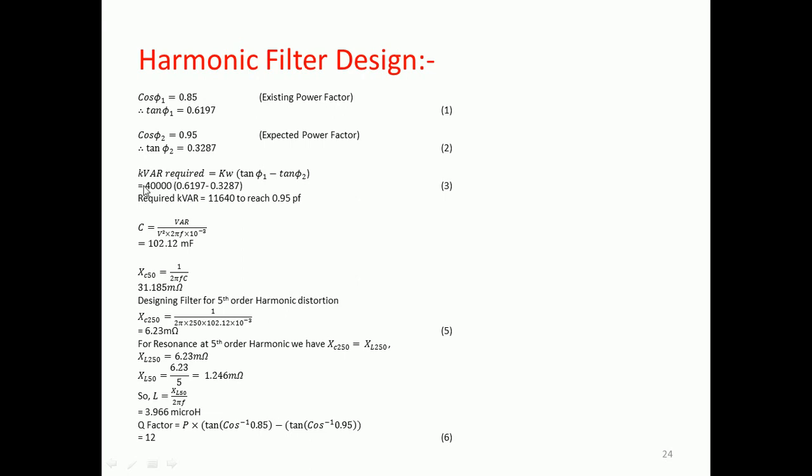The capacity in terms of kW is 40,000. I substituted, and I'll have to find the value of capacitance. Now for Xc, with frequency 50, Xc is equal to 1 by 2 pi Fc. Substituting, you will be getting the value of the capacitive reactance.